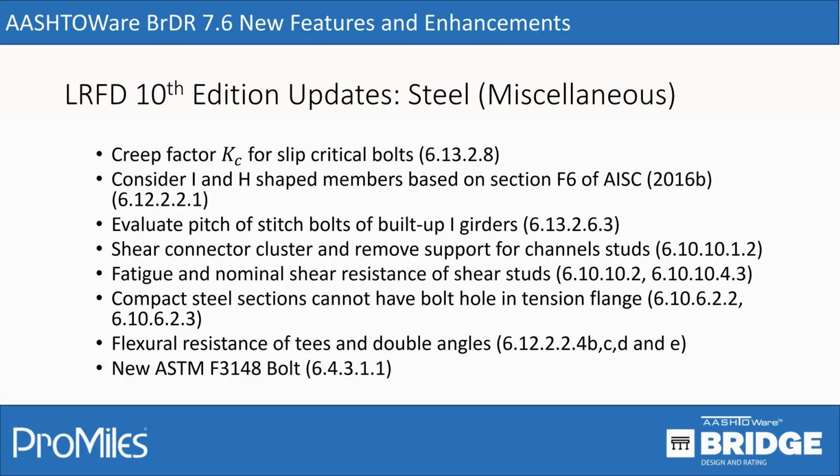But one thing to note here is that we do have a shear stud design tool. The shear stud design tool does not design for clusters. It only designs for the ranges, the original, the previous, or the ranges method of entering shear connectors. Also, support for adding channel studs has been removed from the 10th edition. So there will be no evaluation for channel studs in 10th edition.